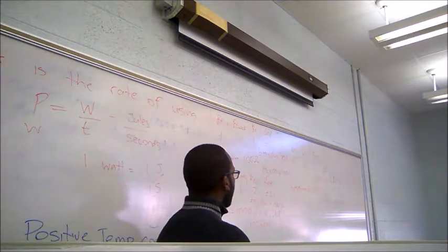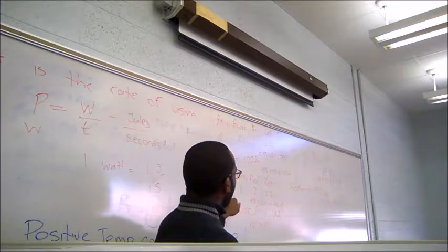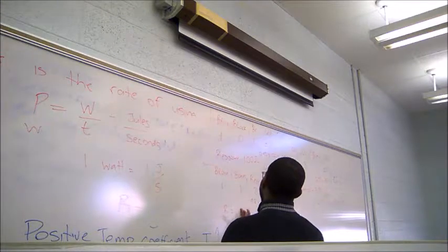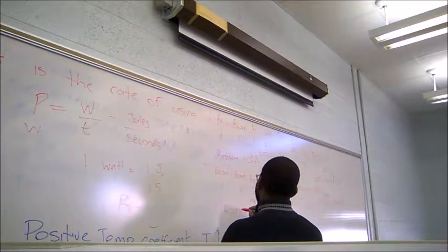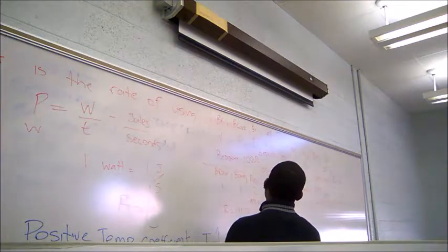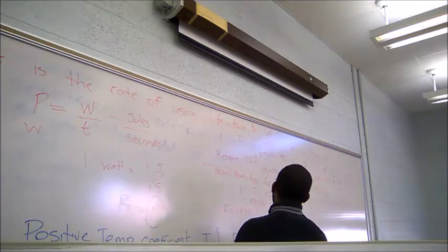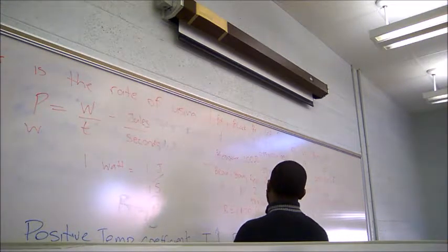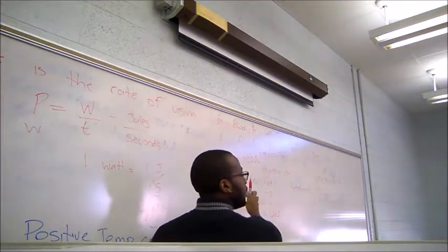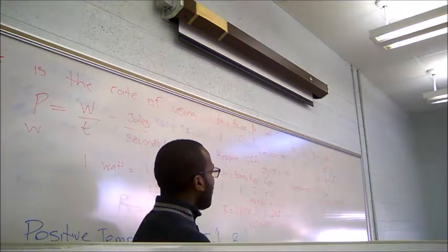Okay, so again, listen up. What's the first number here? 1. What's the second number? 1. Hey, recalculate these two, please. So this is 1.1K. The first number is 1. Second number is 1. The number of zeros is 2. So what is the highest number going to be?